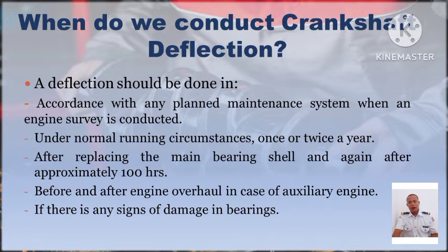It is also done after replacing the main bearing shell, and again after approximately 100 hours following an engine overhaul in the case of an auxiliary engine. So when there are changes, either overhauling or replacing the main engine bearing, we must measure the crankshaft deflection to ensure that all the crank webs are at the proper distance, and that the bearing and other components are not damaged and are in proper condition. Also if there is any sign of damage to the bearing.